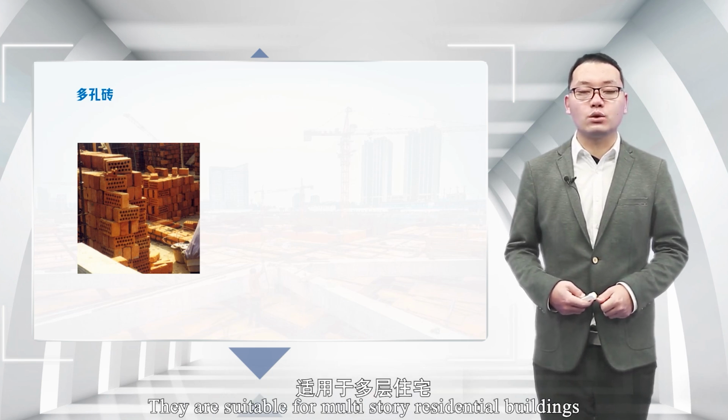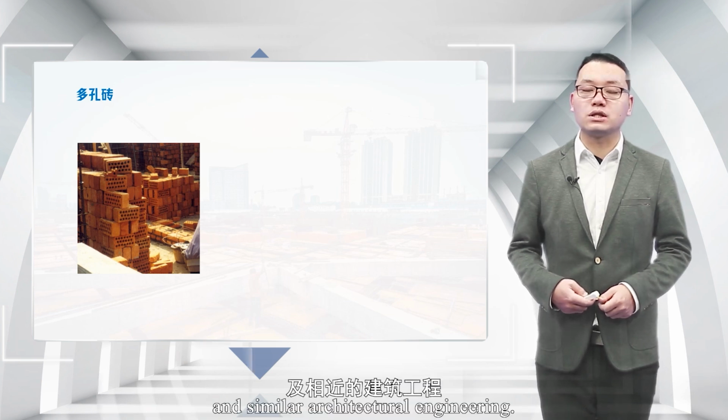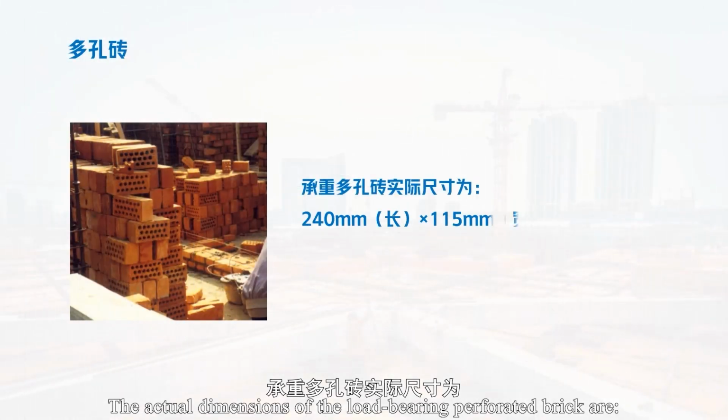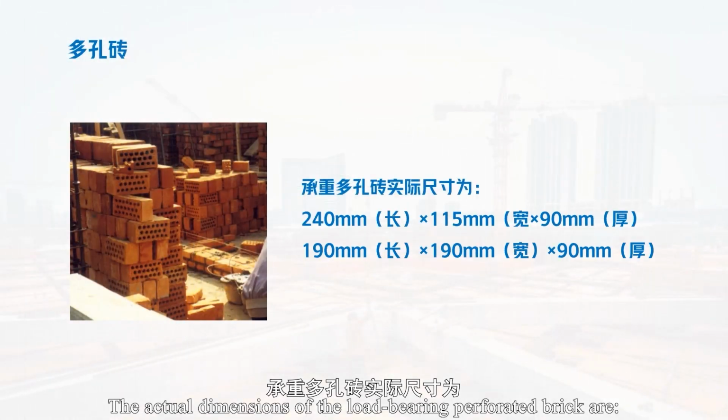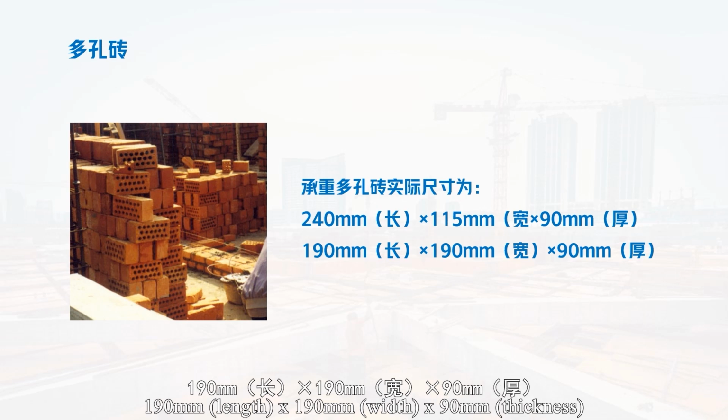They are suitable for multi-story residential buildings and similar architectural engineering. The actual dimensions of the load-bearing perforated brick are 240 mm length x 115 mm width x 90 mm thickness, and 190 mm length x 190 mm width x 90 mm thickness.